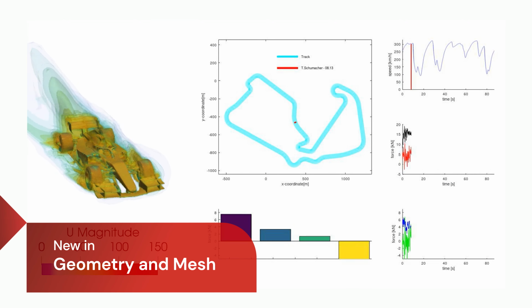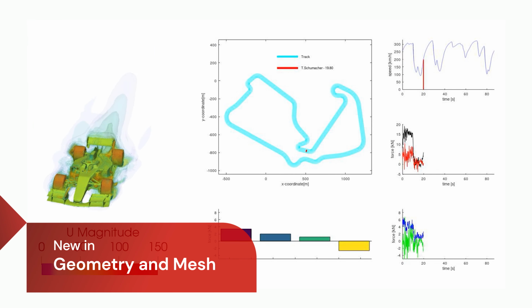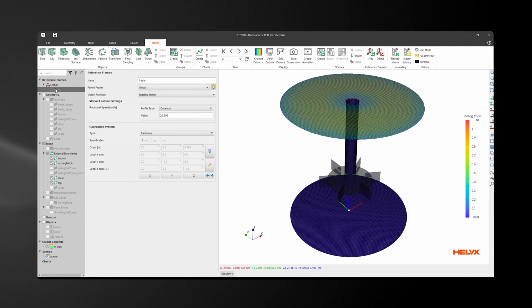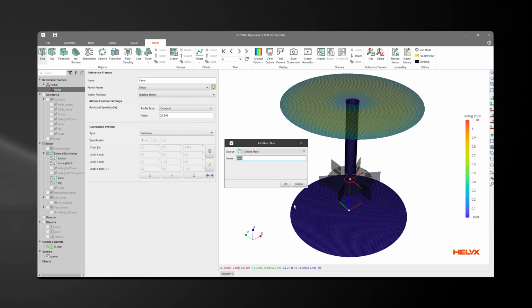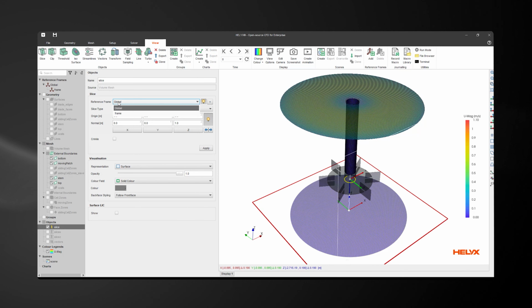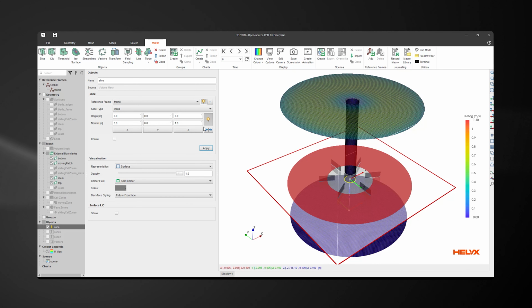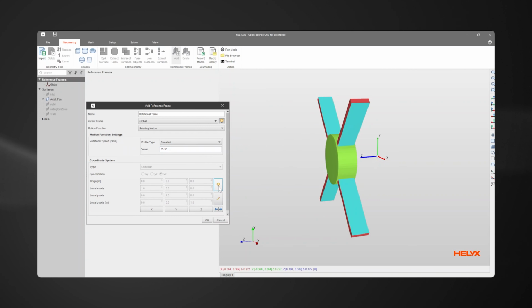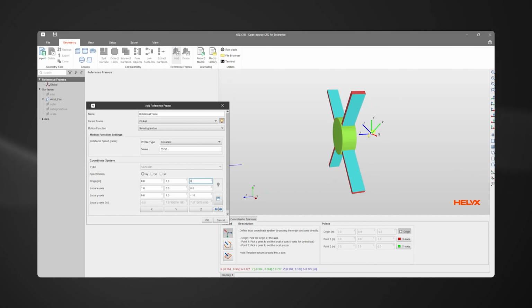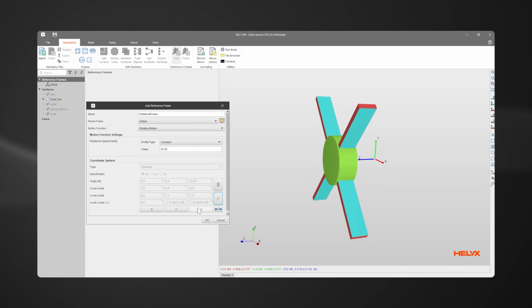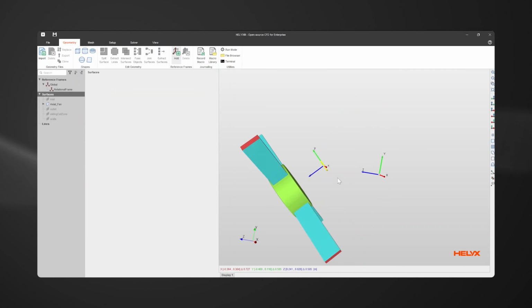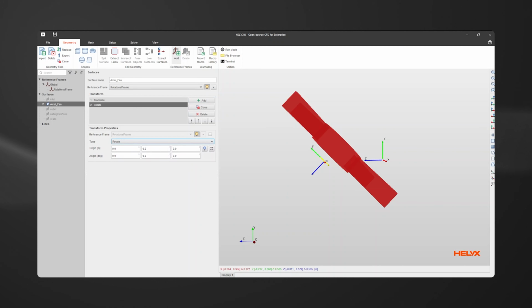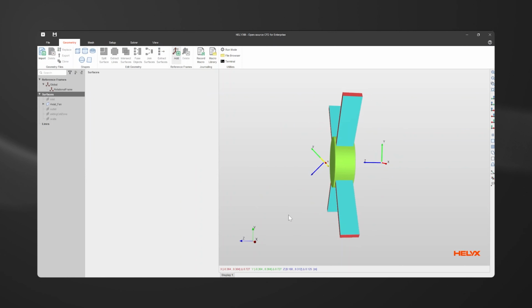In version 4, we introduced the concept of reference frames that was limited to a few solver components. Now, in version 4.3.0, we incorporated the concept of reference frames for nearly everything that can be done in HELYX and ELEMENTS, including geometry manipulation and mesh generation. In terms of the Geometry tab, any transformation to geometry surfaces can be applied with respect to the standard global reference frame or to a user-defined local reference frame. Each separate geometry surface available in the Geometry tab can make use of a different local reference frame for easy alignment or replacement, for example, in parametric studies.